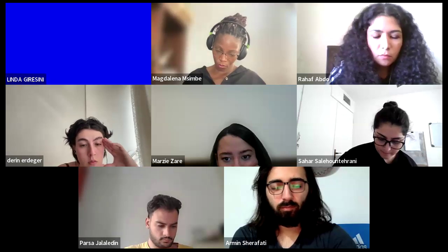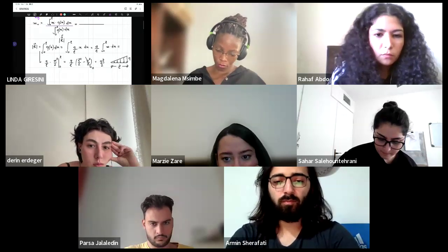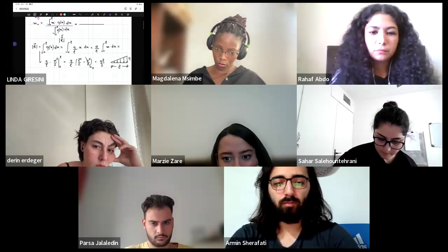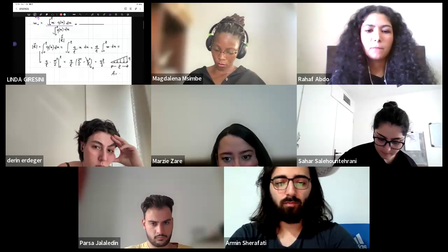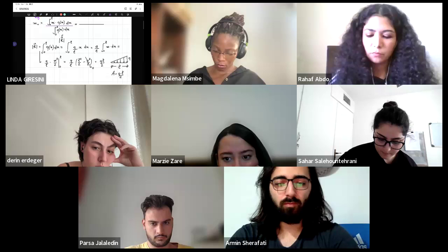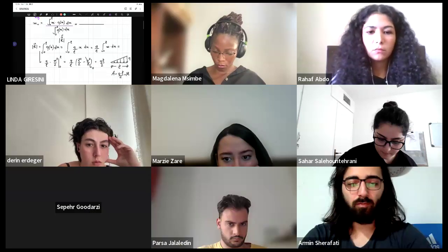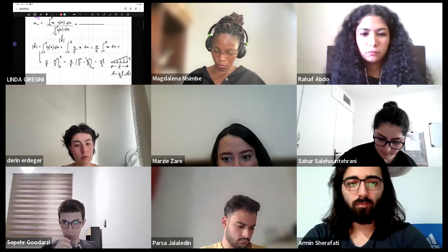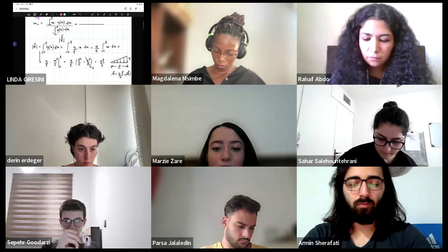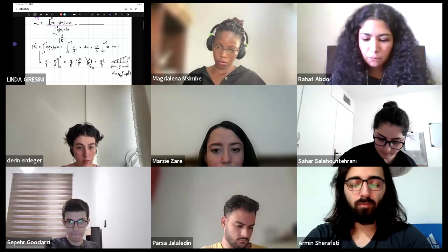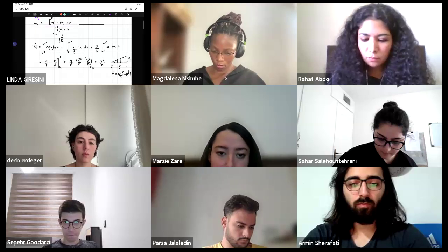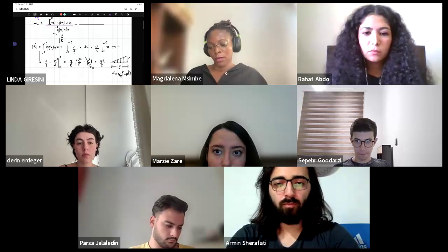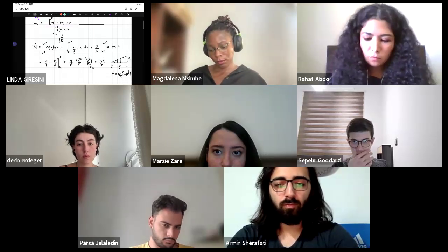The area of this triangle, because it's a resultant. So the area of this triangle is equal to qL divided by 2, and this is also the magnitude of the resultant. So you don't need to refer to integrals, which sometimes are very difficult, but it's very simple because you can understand that the resultant force is actually an area.